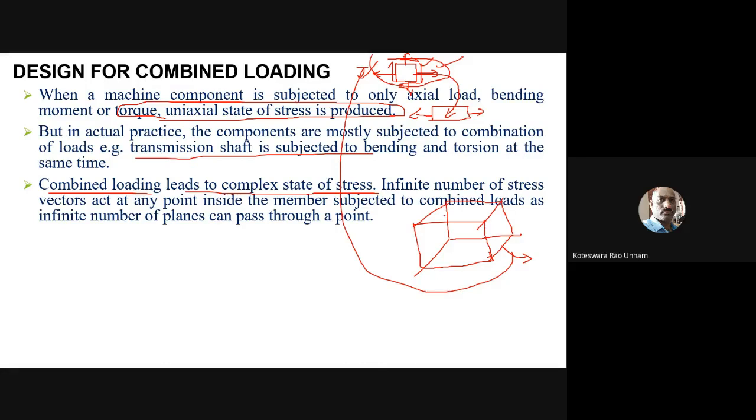Here is how I can reduce from triaxial to biaxial. If I take these three axes, x, y, and z, this is the triaxial state of stress in all three directions. If stresses are zero in any one direction, let us say all the stresses acting in the z direction are zero, I can remove those and consider only one plane, with the x direction and y direction.